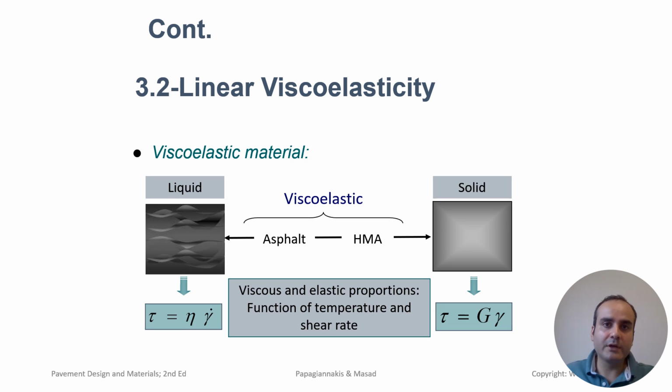Solid materials respond to shear strain in a manner that reflects their rigidity and elasticity. Solids have a definite shape and structure, meaning their molecules are tightly bound together, which resists deformation. In terms of elastic solids, materials such as metals, concrete, or asphalt, shear strain causes the material to deform but not flow. These materials can return to their original shape once the shear stress is removed, provided the stress does not exceed a certain limit, which is called the yield strength or elastic limit.